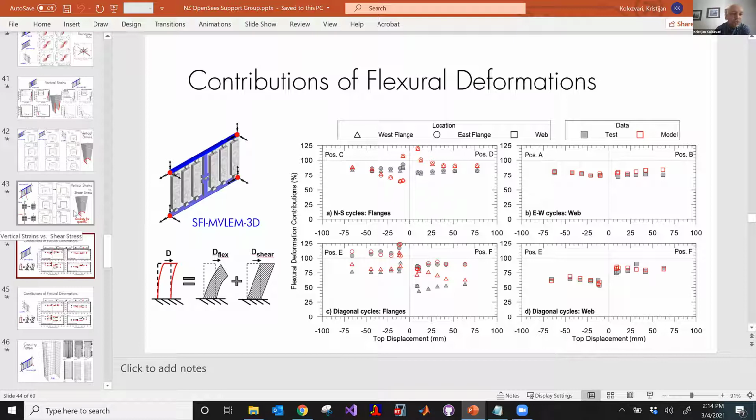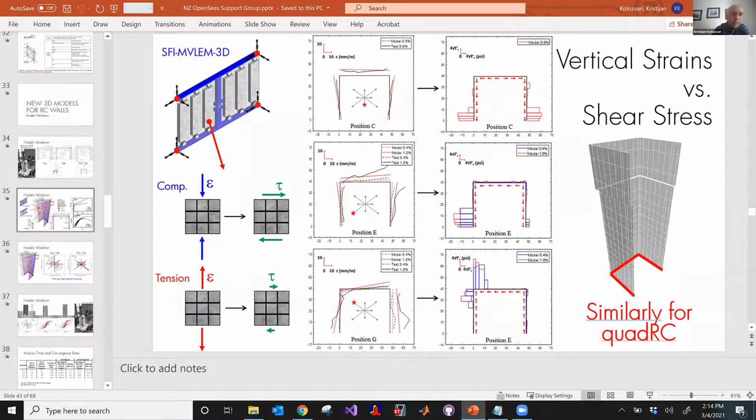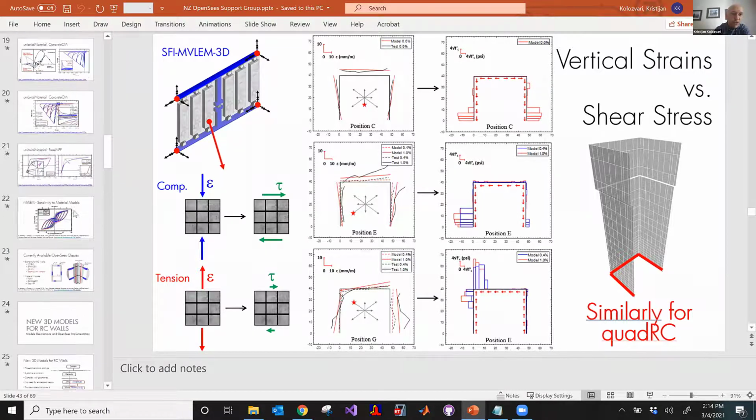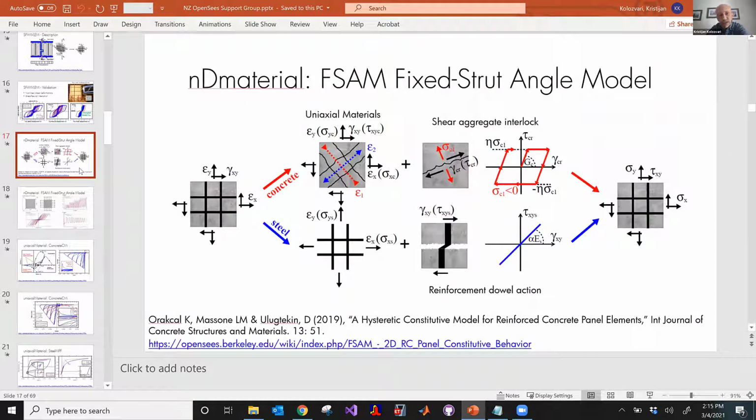It's kind of an unusual configuration. I believe there needs to be some extension to this material model in order to do that. This one over here, it's possible. Currently this reinforcement is only horizontal and vertical, but it's very simple to modify it to add an angle to it, and that will enable that type of modeling. But currently no, the reinforcement is only vertical and horizontal.